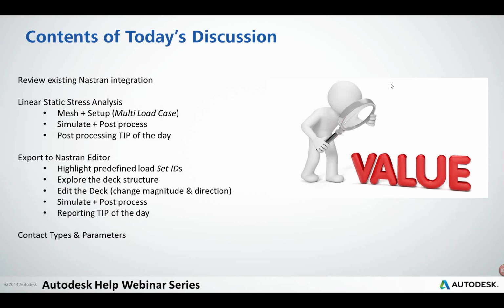And then I will highlight exporting our setup to the Nastran editor that is included with Simulation Mechanical, and talk a little bit about what the Nastran file looks like. And I will highlight the predefined load sets that we have created using multiple load cases, and I will explore some of the deck structure, and I'll touch on editing the deck, changing the magnitude and direction of certain loads in different load cases, and having full control over that using the Nastran deck.